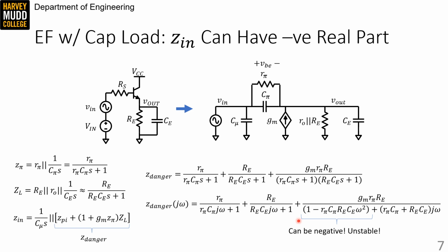If you find a negative impedance, that's identical to finding a pole on the right half plane, but you can also think of it as meaning that when you decrease voltage, more current comes out, which you can imagine would be an unstable behavior. So if this term is big enough, it leaves us with a negative real part, and that makes the emitter follower unstable. So be super careful if you're using an emitter follower to drive a large capacitive load, because that makes this CE part big.